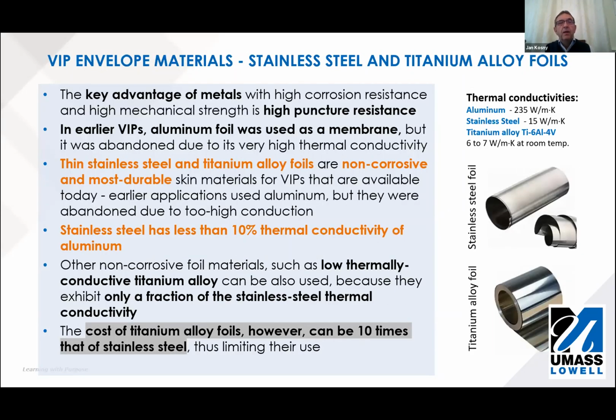Talking about membrane materials, historically aluminum was the major application as a membrane, first as aluminum foil in the earliest applications. Later it was replaced by less conducting stainless steel, and then in super applications right now we are using titanium alloys, which are less conducting than stainless steel, but they are 10 times more expensive.